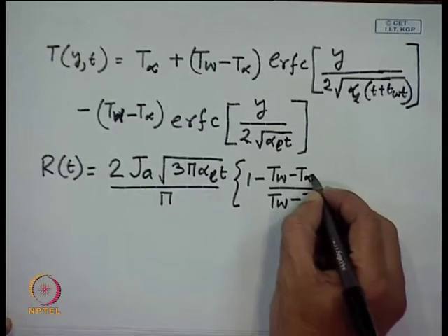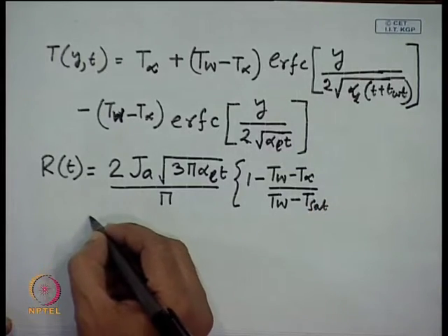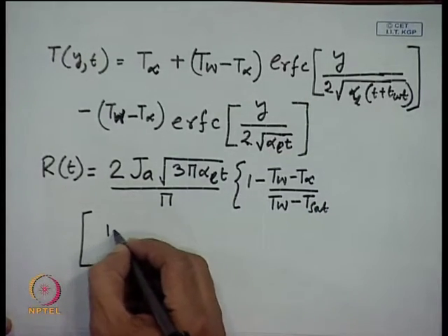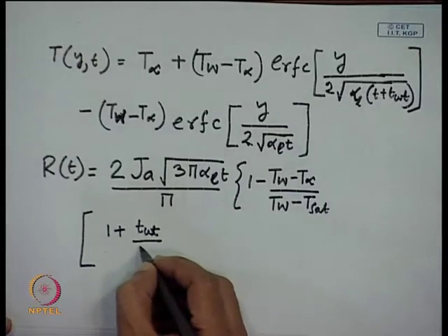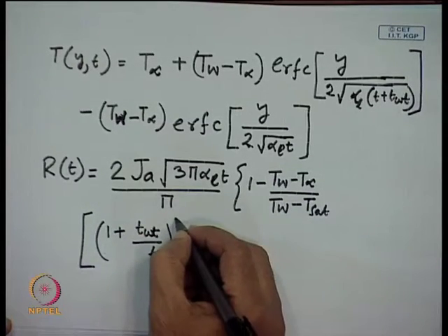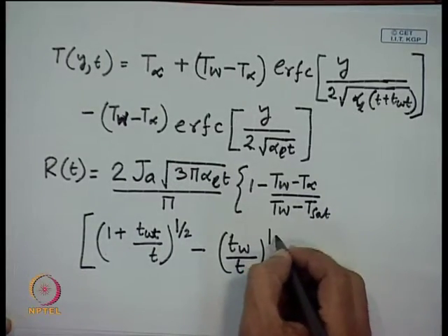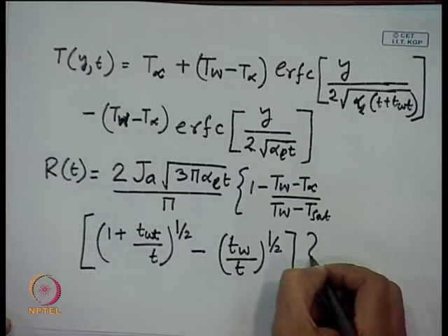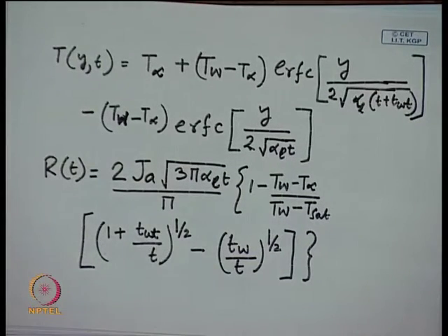So, all sorts of temperatures are important here, that means wall temperature, saturation temperature and the bulk liquid temperature, and with this the times are also important. This is the time at which we are interested to know the bubble radius. Okay. So, by this then we will get what is the radius of the bubble, how the radius of the bubble changes with time.